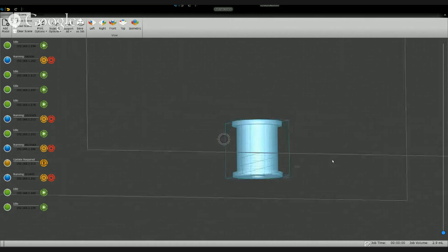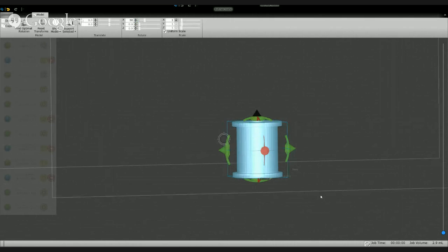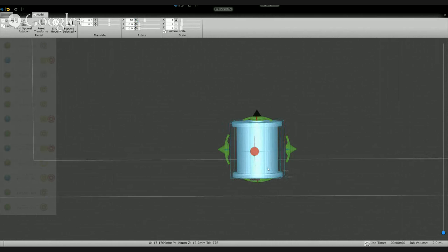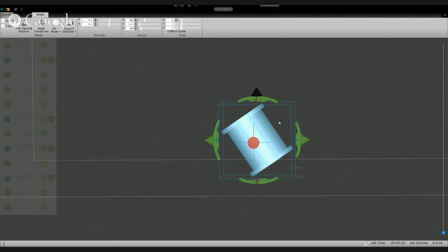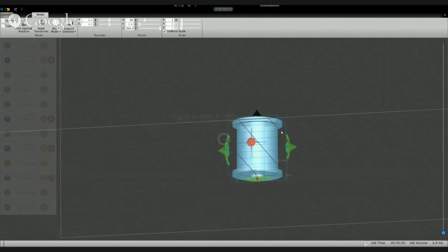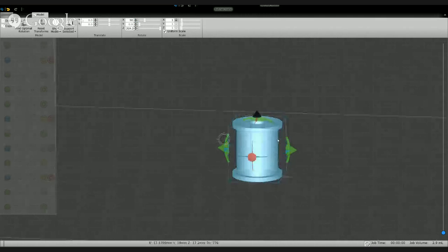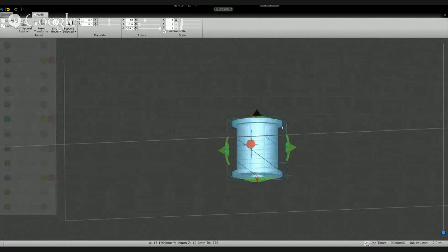If you want this height to be dead accurate, then you'll need to support the model and raise it up. And in that case, you'll probably also want to angle it so that the downward facing surfaces are minimized. So if you print it directly like this, you'll get nice surfaces everywhere. This lip overhang is fine. It's only about 1 millimeter, maybe 2, and that's fine.